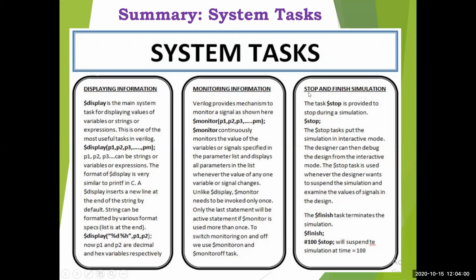Then finally, we have seen $stop and $finish simulation. We have another two system tasks. $stop is provided to stop during a simulation, and it is written like this; it does not have any argument list. The $stop task puts the simulation in interactive mode. The designer can then debug the design from the interactive mode.